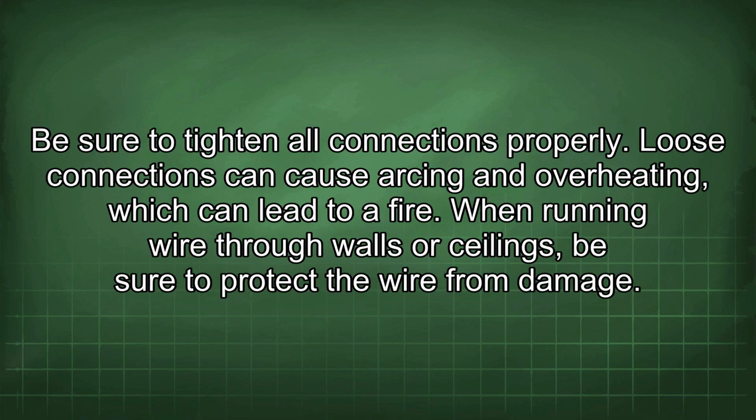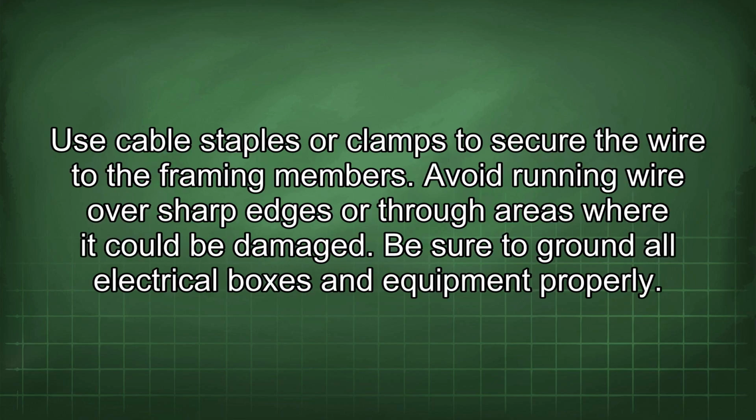Be sure to tighten all connections properly. Loose connections can cause arcing and overheating, which can lead to a fire. When running wire through walls or ceilings, be sure to protect the wire from damage. Use cable staples or clamps to secure the wire to the framing members. Avoid running wire over sharp edges or through areas where it could be damaged.